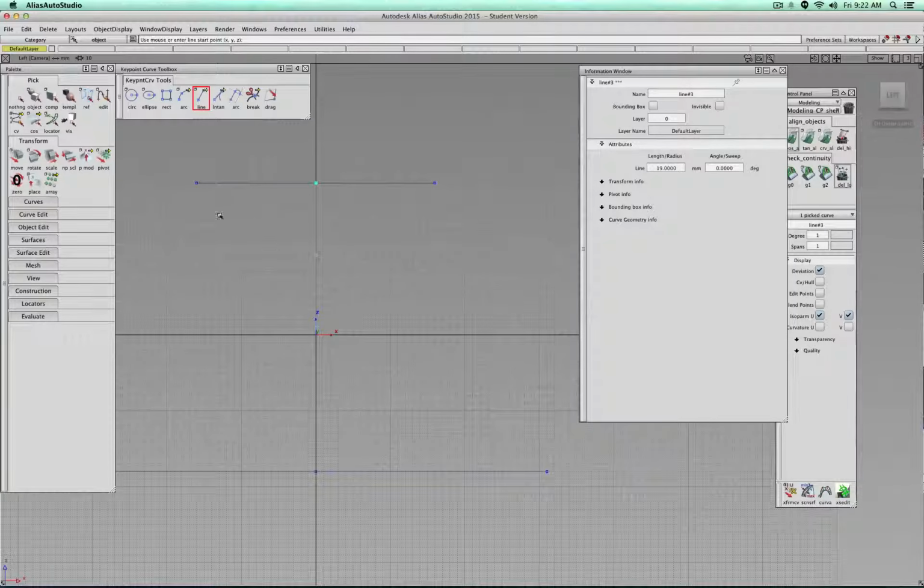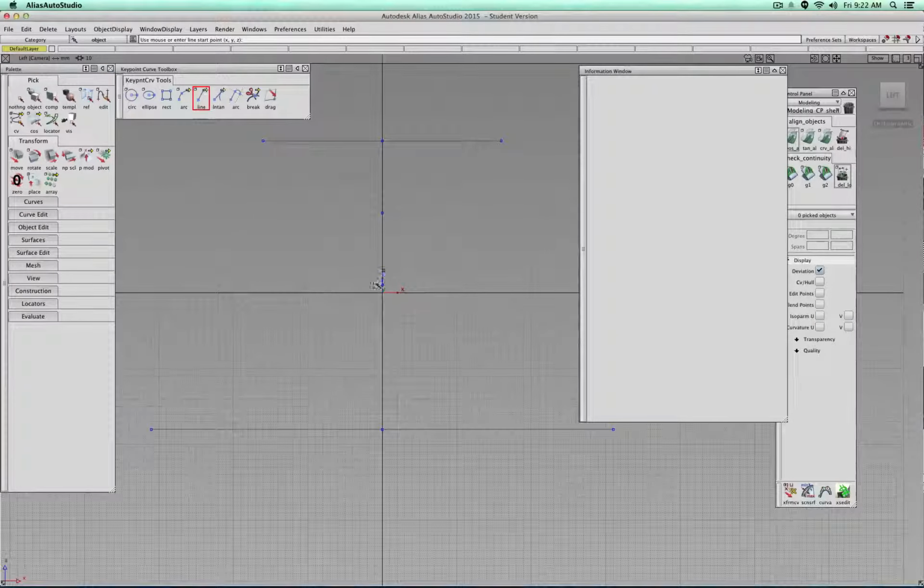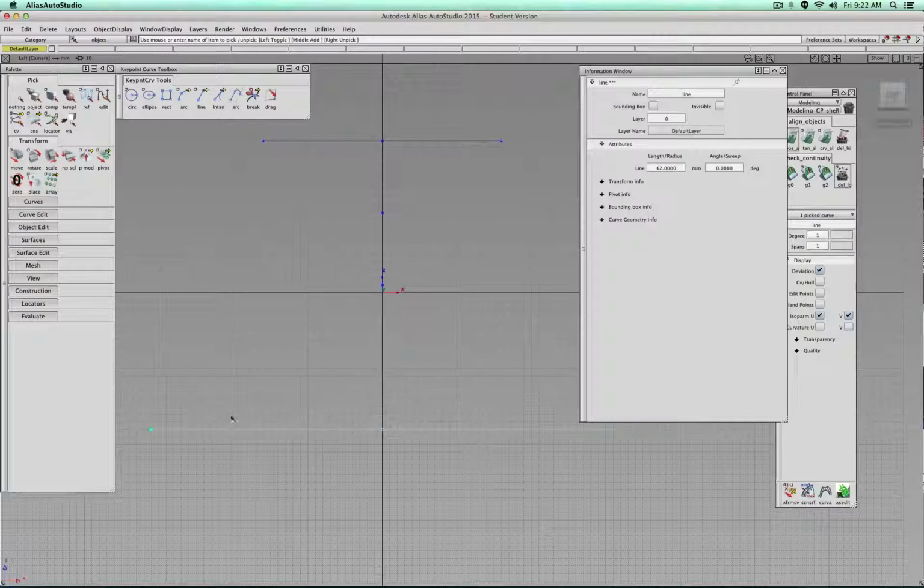So I know, for example, now where this base has to go to. So I can select nothing, select object, select my part, go to move, and then with the grid move it up. And I'm just repositioning the pivot point position till my midpoint, you see, along the z-axis is actually snapping.